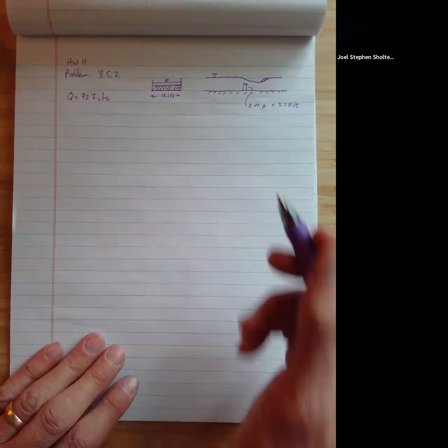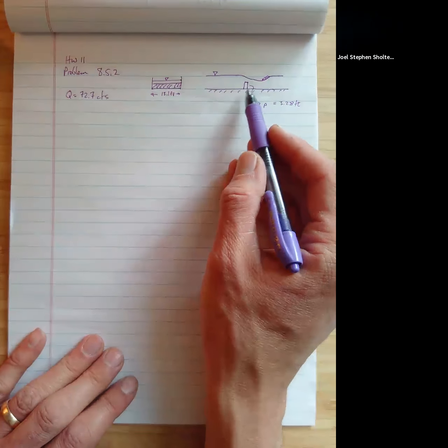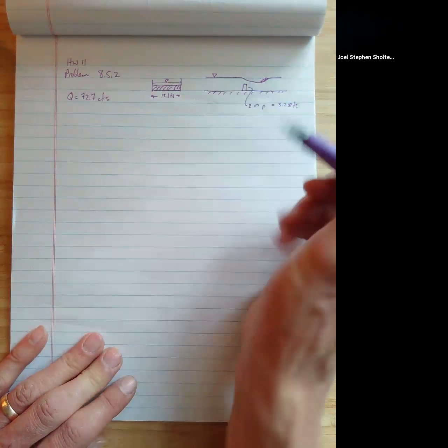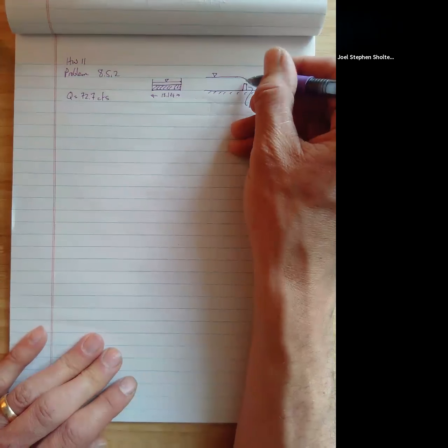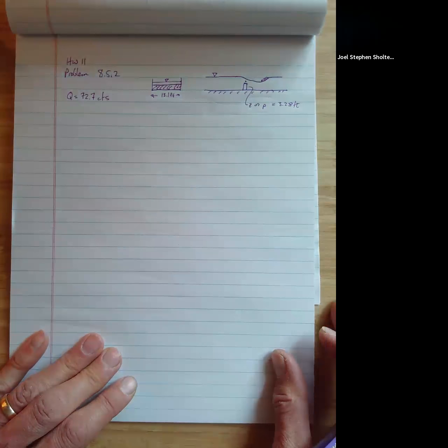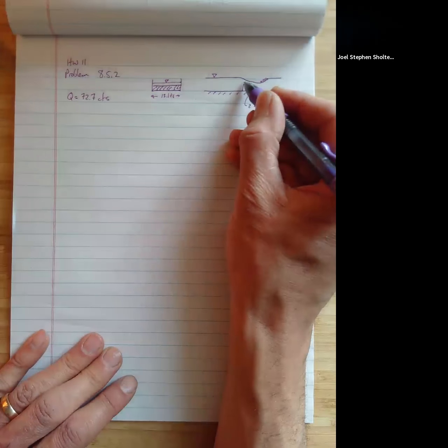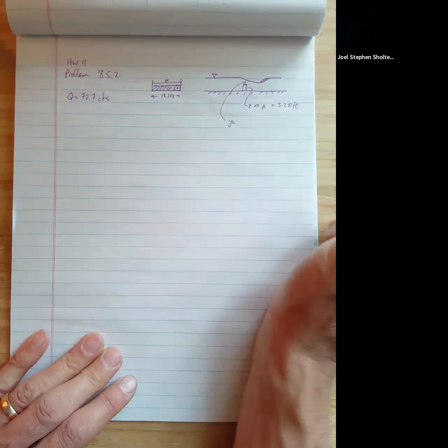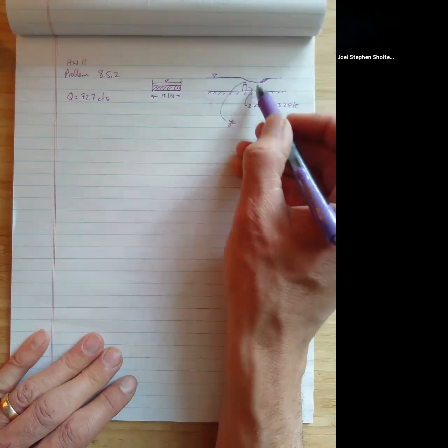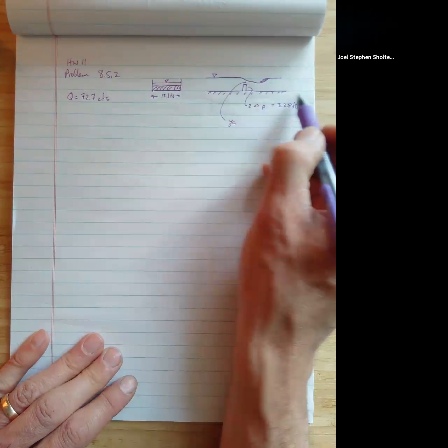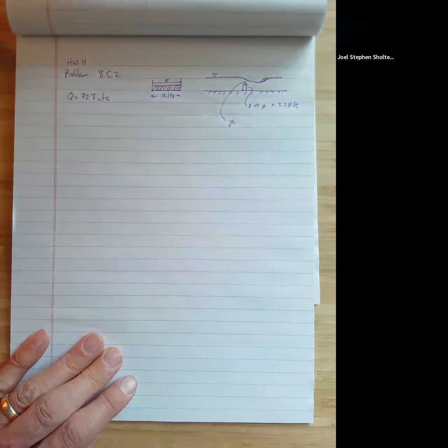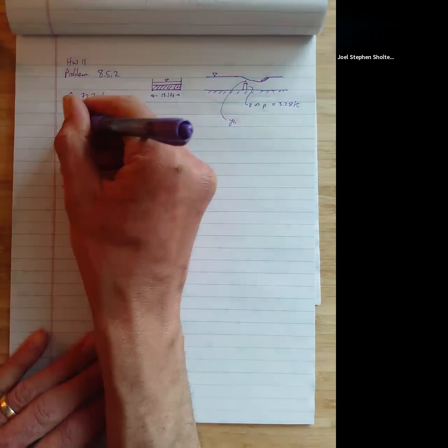Well, what's the first thing we know about weirs? They cause critical depth to happen over them. So the first thing we work with is we know that critical depth is occurring over this weir, right there. So YC. And then maybe it slips down into supercritical flow as it goes over. And then if the slope stays the same, we'll get a hydraulic jump and then we'll go back to subcritical flow. Okay, so YC, let's calculate YC.